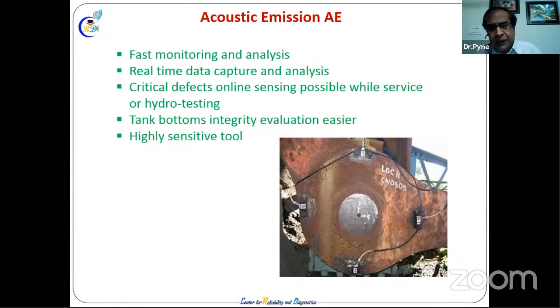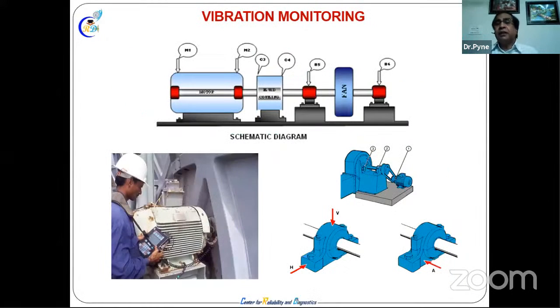Okay, acoustic emission: in a pressure vessel, if anything is happening, any creep going on, you cannot see creep. So if you put acoustic emission sensors, piezoelectric accelerometers, at different places, you will see different distances. You can find out the real-time problem happening over months and years in an asset that you are doubtful about or that is critical. So other techniques are available.